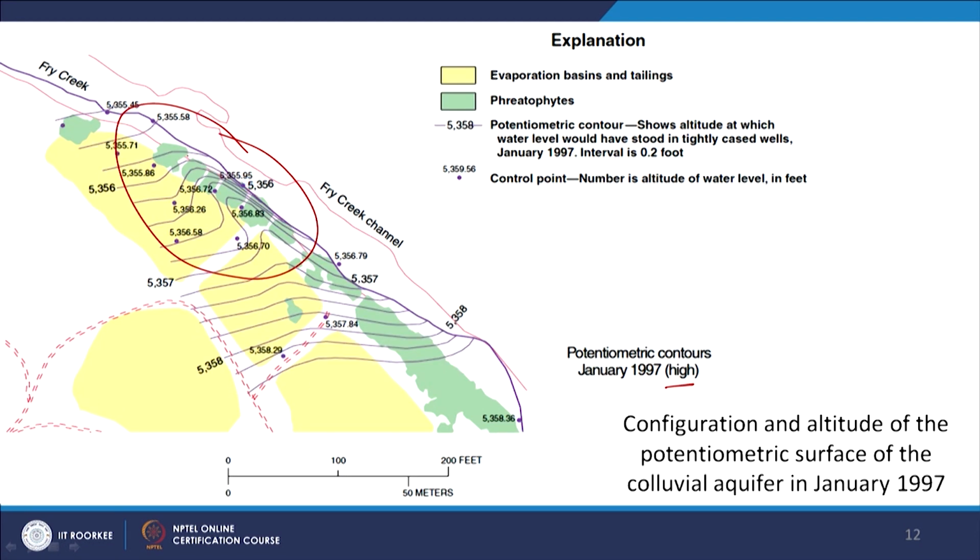So, obviously depending upon where I am putting in my PRB, I need to be very considerate of these changes in groundwater flow direction. Why is that? Otherwise the groundwater flow lines can flow around the PRB, right. So, that is something I need to be concerned with.